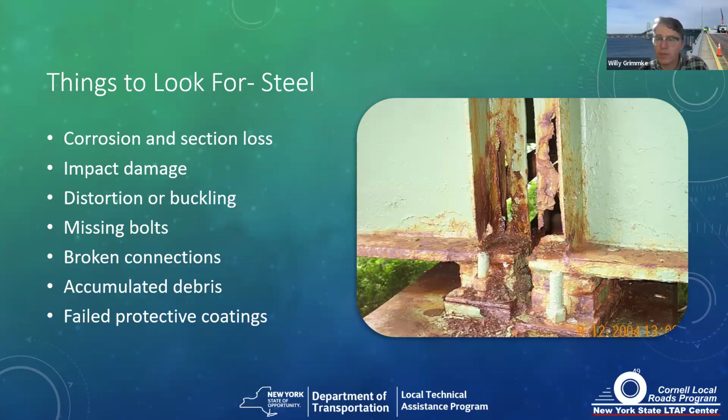Quick aside, we had a number of weathering steel bridges in Washington County, and they were not in the environment that was ideal for weathering steel. And what would happen is, rather than the tightly adhering patina developing, we would start to get flaking and accelerated rusting. In the photo, we can see that A, the coating is failing, and B, we're getting corrosion and section loss. This is over top of a pier under a joint, which apparently has been leaking for quite some time.